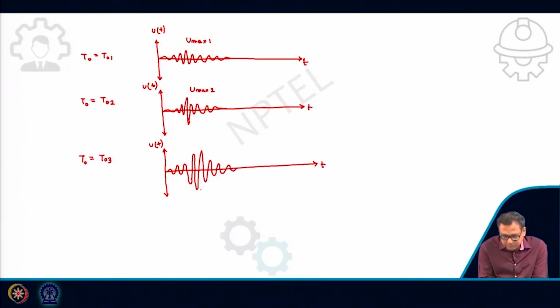So suppose this is my U max. This is 3. So now for different time periods I will get different maximum values of displacement by applying the same response, or the same ground motion, to different structures on similar types of soil and for a particular damping ratio, because it is a function of time period and the damping ratio.